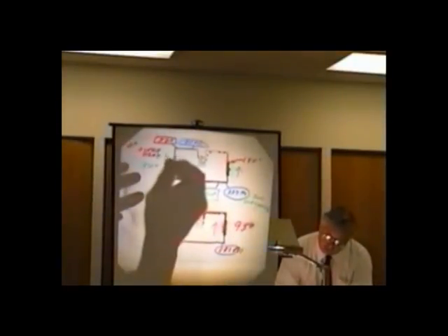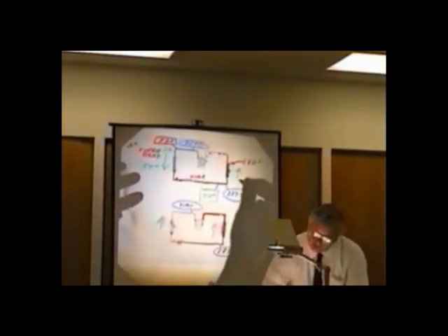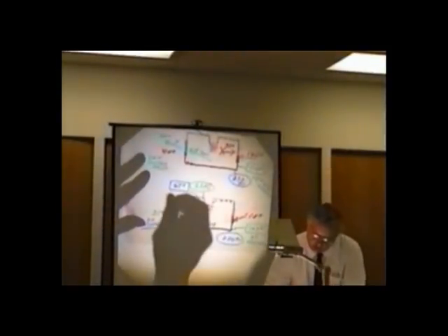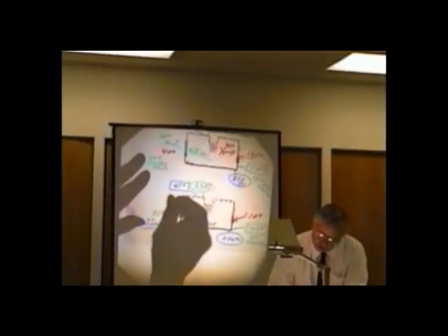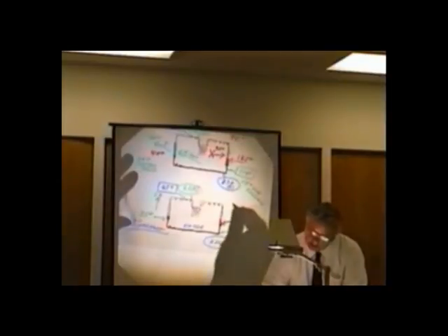And the superheat went down. So superheat goes down, subcooling goes up. Let's go back. On an undercharge, my superheat went up and the subcooling went down.